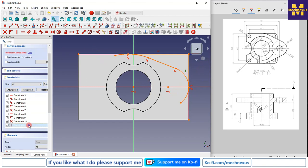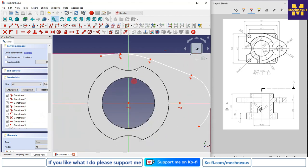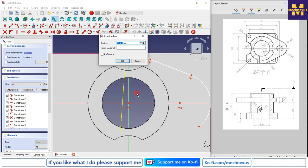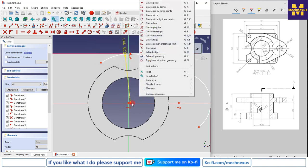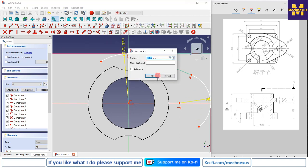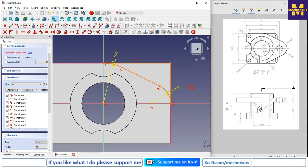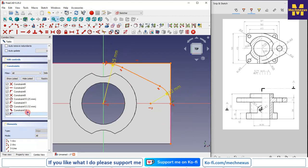Now I will delete this conflict constraint and this is the 25. And this is the R12. Now I will trim the unnecessary geometry, and here I will remove this constraint.